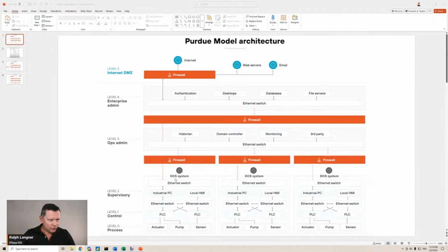And down here, then you have DCS system. That is a distributed control system, that's the acronym. That is not necessarily something that you will always find, because DCS is our thing in the process industries, where it's about liquids and gas manipulation, etc. You will not find a DCS in manufacturing, discrete manufacturing, where you're producing pieces, small little pieces, or even large pieces, like in automotive manufacturing.